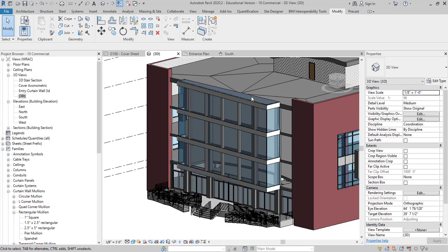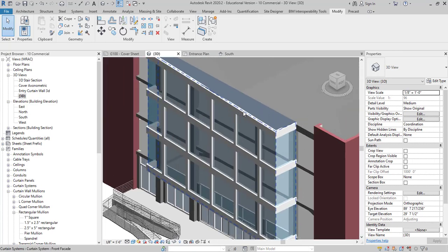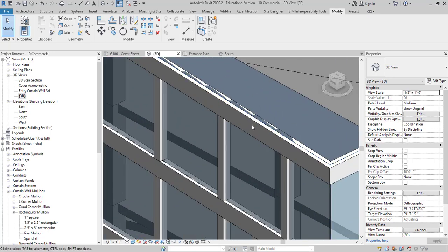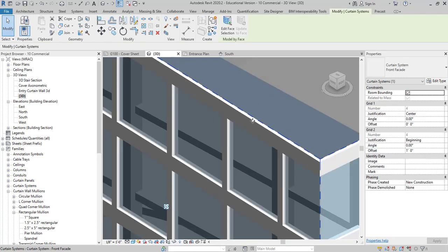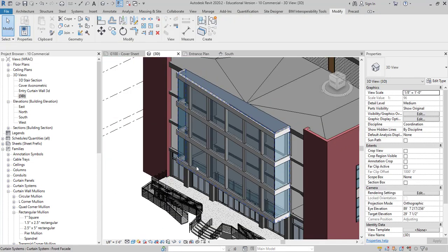Unfortunately, Revit has tricked us into thinking we're done. There are actually, however, 2 separate mullions in this location, and here's why. There is a curtain system that runs 12 foot on center, and that's what we offset, 12 inches. So we started at 38 negative here and came up to 0. Starting counting down here, we moved up 1 foot, then we went 12 feet, 12 feet, 12 feet, then we moved down 1 foot. But we also have a border pattern on these,